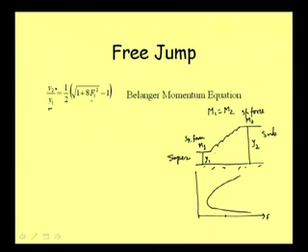Okay, and then a lot of eddies form in this way, and then some flow moves this way, and now because these eddies are forming here, energy gets lost in this part. So energy dissipates here in this portion, and that's why the energy of upstream and energy of downstream is not equal. There is a significant difference of energy, and that's why the hydraulic jump itself is used for energy dissipation.